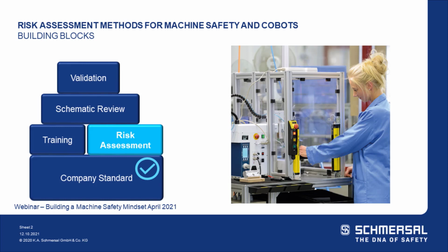Now, however, this machine that I reviewed had safety light curtains that triggered the press to stop, and they were wired correctly to a safety relay. So I instantly thought it was odd that a machine with safety light curtains could allow for an amputation, right? The wiring was correct, the distance from the hazard looked about right. So the accident was not typical, right? Somebody took the time to add safety controls properly.